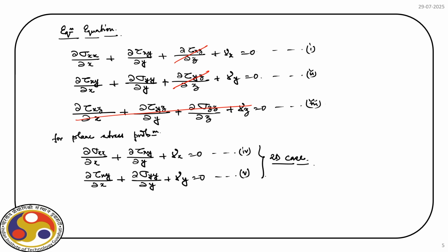And that completes the derivation. So, if we have a plane stress problem, it is defined by sigma xx, sigma yy and tau xy. Then from this 2D stress field, we can find out sigma n, tau n, then principal stresses sigma 1, sigma 2, and of course, their directions also we can find out, which I am not going to explain for the time being, because we have already derived that. And finally, we have the equilibrium equation for plane stress problem. So, with that, let us close here.